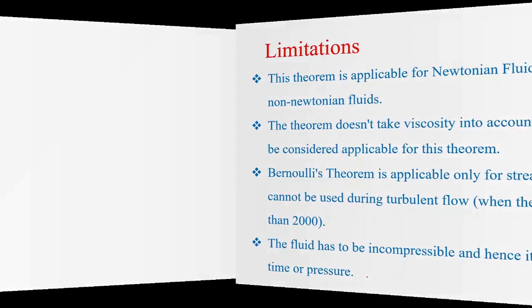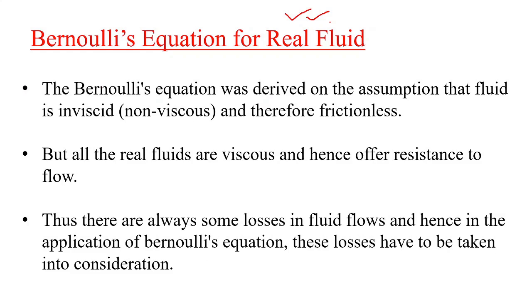So what will be the Bernoulli's equation for a real fluid? In the practical way we are encountering real fluids only. Bernoulli's equation was derived on the assumption that the fluid is non-viscous, that is inviscid, and therefore frictionless, because it's an ideal fluid. But all real fluids are viscous and hence offer resistance to the flow.